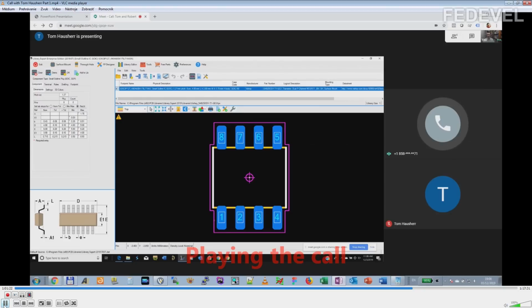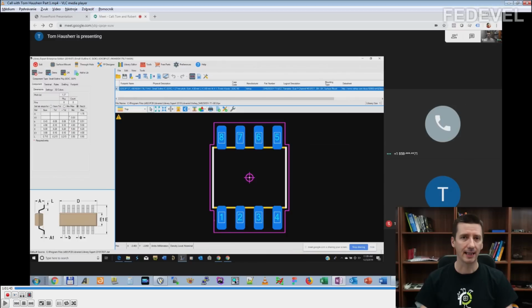Yes, you have to have some kind of knowledge. I took the CIT certified J-STD-001 class for one week or whatever, and I learned how to solder parts. I think every PCB designer should learn how to solder parts to boards. Once you learn how to solder a part to a board, then you know a good pattern from a bad pattern. Yeah, I completely agree.